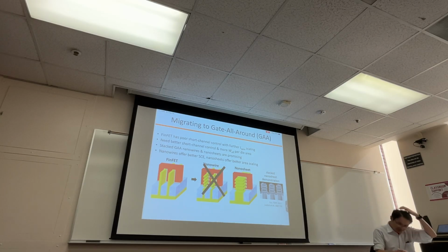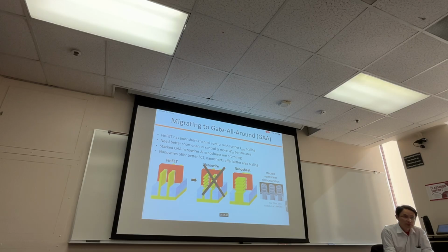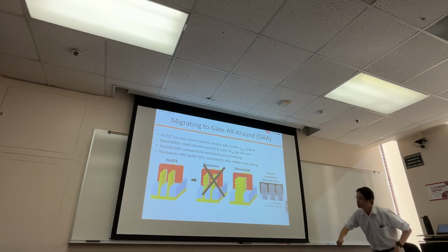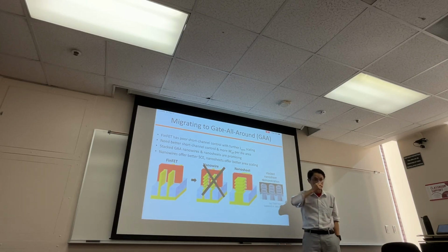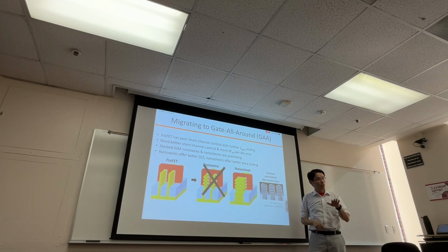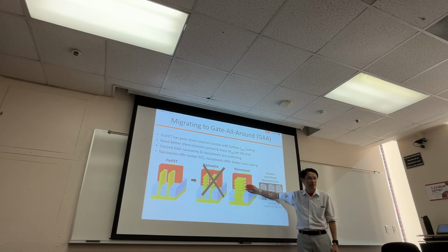So for the stacked nanosheet shown, do they usually use it as one big gate, or is each transistor connected to a different gate? Oh no, all these are shorted together, right? So this is one transistor. Okay. If you want to do that, okay, separate this. So this is one transistor and another transistor.